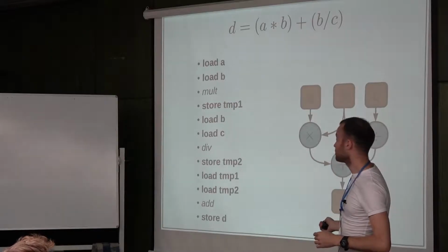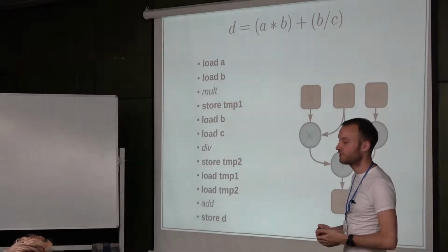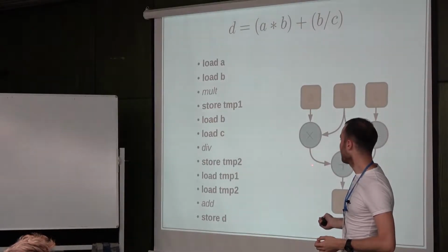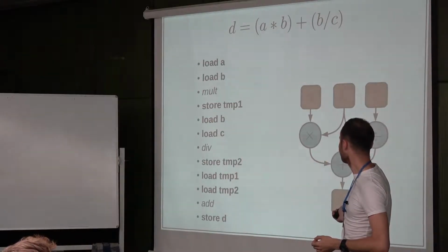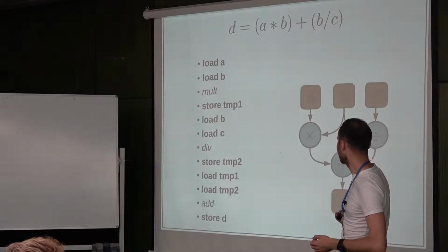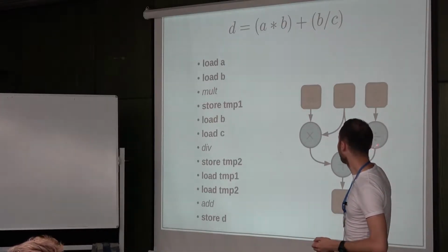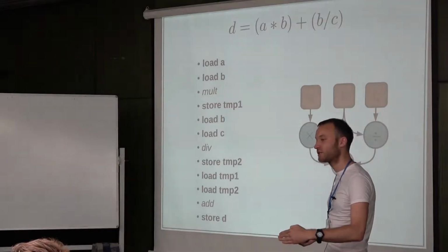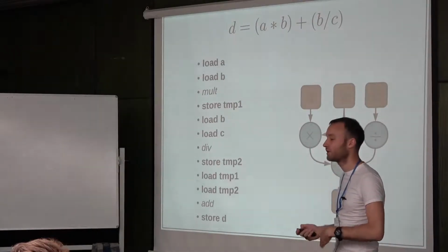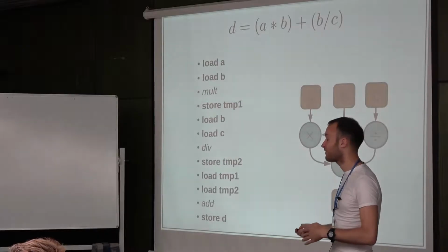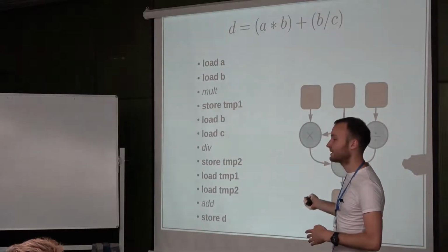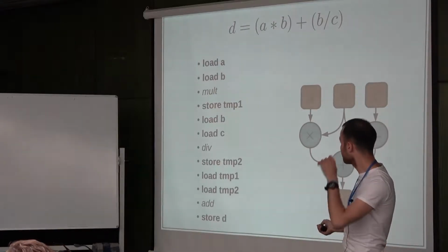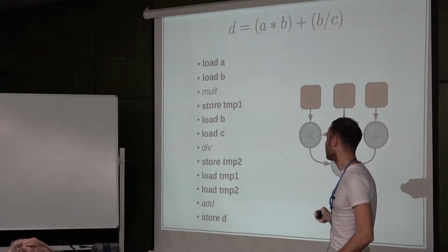The one thing that I don't show here, and it's a standard convention for FPGA community, we don't explicitly show flip-flops between the blocks. So it is assumed that operation itself might have several stages. So multiplication is normally not one clock cycle. So we have internal memory blocks inside each computational unit, and we have memory blocks, registers between them.